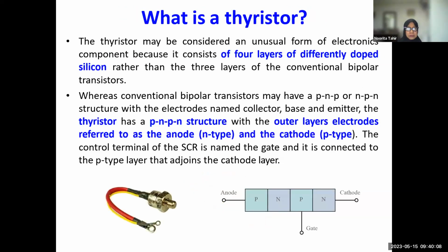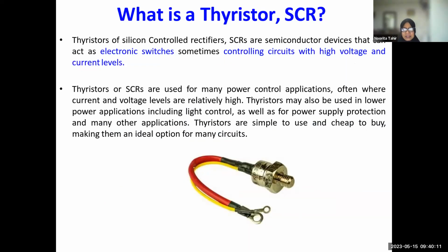Okay, so bipolar junction, field effect and insulated gate field effect transistors are all non-hysteretic devices. They do not inherently latch into a state after being stimulated by a voltage or current signal. For any given input signal at any given time, a transistor will exhibit a predictable output response as defined by its characteristic curve. That is for the hysteresis earlier.